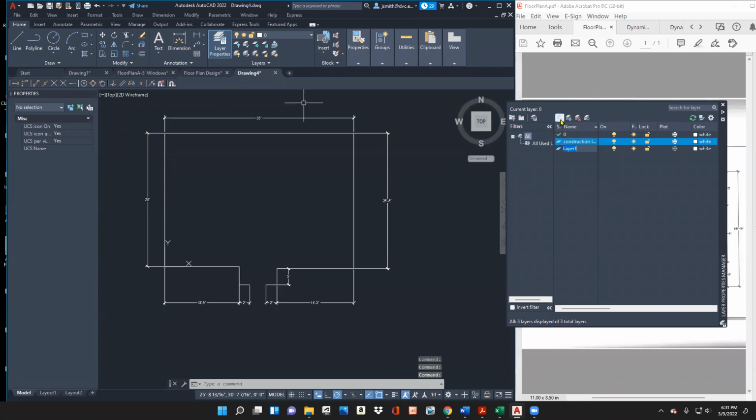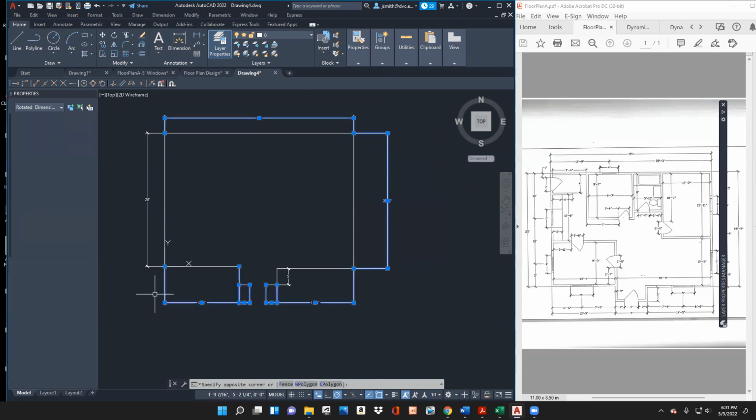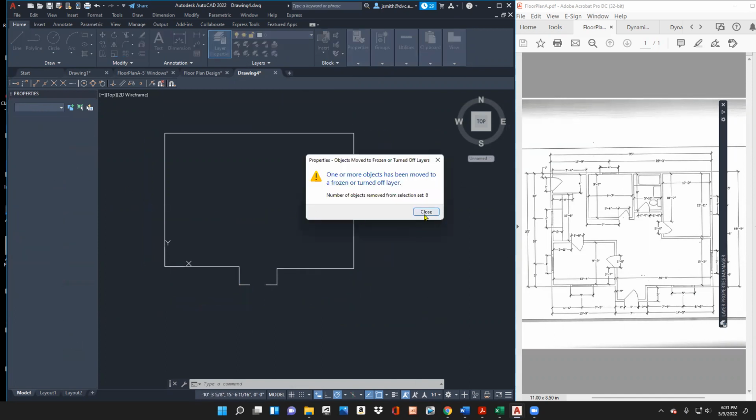So typically you would do walls, and then you could do doors. I'm just going to do a couple of them, and I'll just do dimensions also. What you can do is turn something off, and to verify it's working, I'll select all my dimensions, right click, say properties, and I'll say layer, and I'll put it in the dimensions layer, and they should all disappear.